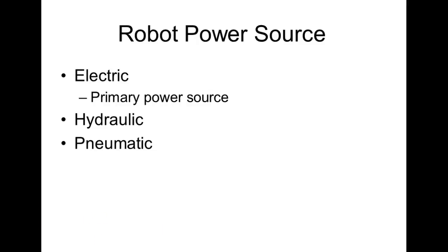So the amount of force we generate in a fluid system, they call it Pascal's law, by the way. So force, how much force? Force is something that you apply to cause it to change shapes or change directions, right? It's equal to the pressure that you're applying times the area you're applying that pressure to.